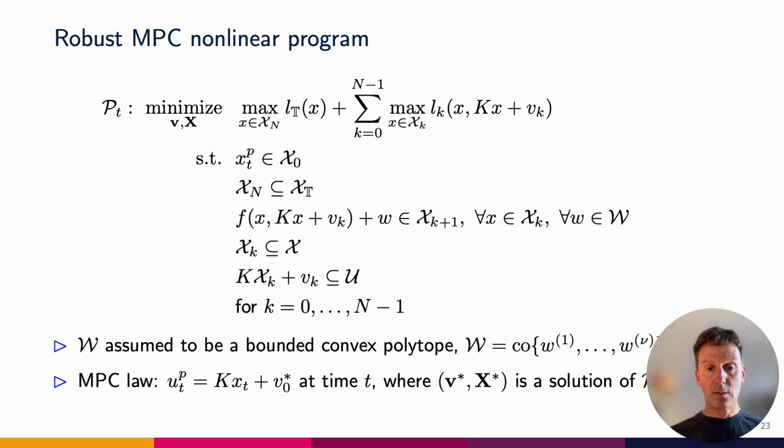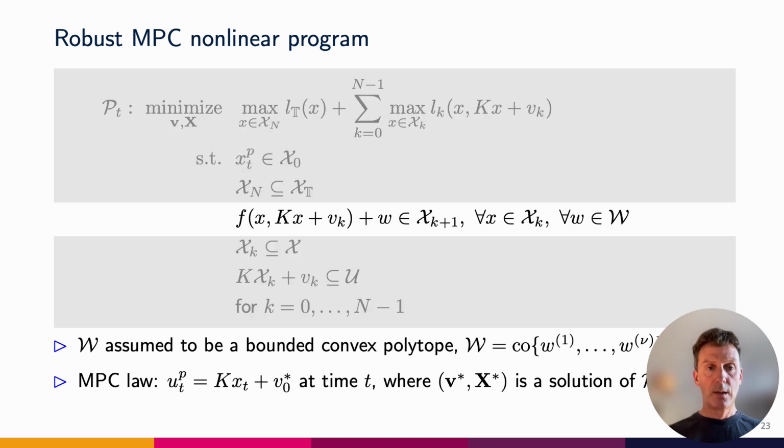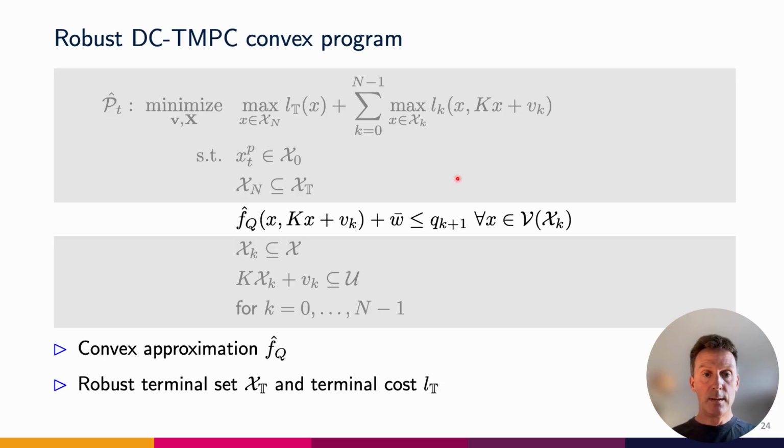In the next section of this talk, I'm going to return to the problem formulation and explain how we can incorporate explicit disturbance handling in the MPC strategy. So I'm assuming that we have additive disturbances affecting the system model, and we have bounds on these disturbances. We need to use the bounds on the disturbances to modify the constraints that define the tube bounding the reachable sets for our predicted states.